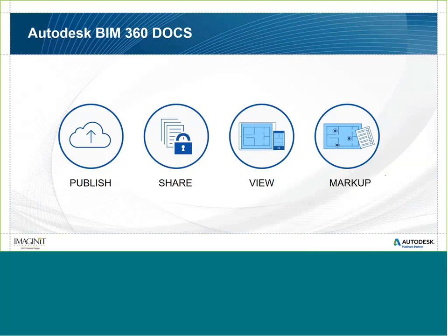Obviously here, this is also becoming a viewer. So you can view any of the common design formats that are out there. So right now, BIM 360 Docs basically supports up to 40 different formats that are related to design type formats. So PDF, AutoCAD, MicroStation, Navisworks, SolidWorks, Inventor files can all be viewed directly in this environment. So that you don't have to have separate software to download and know how to use just to look at something. So anyone who has enough skill to basically use a tablet device can view a 3D model, can view plans, all of those things.